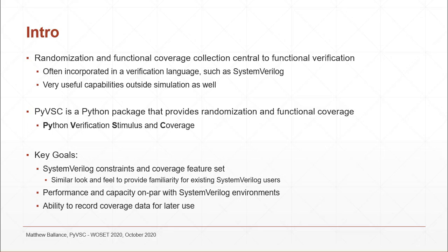Using randomized stimulus and coverage is very useful outside of simulation-based verification as well. And oftentimes we either see dedicated libraries used for this purpose, or sometimes users will leverage the capabilities of their simulation-based environment, SystemVerilog, as a way to get these capabilities.